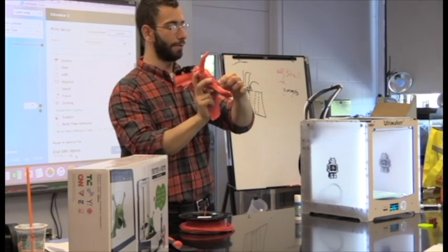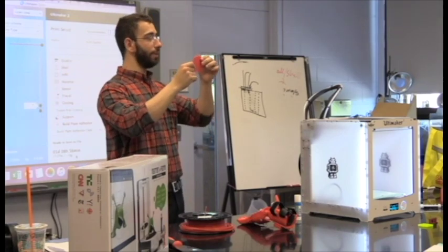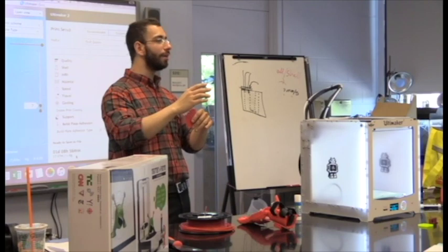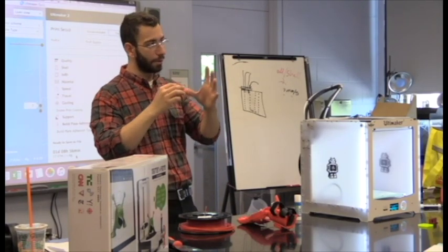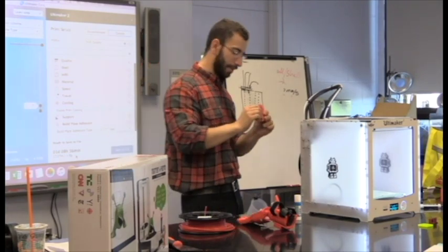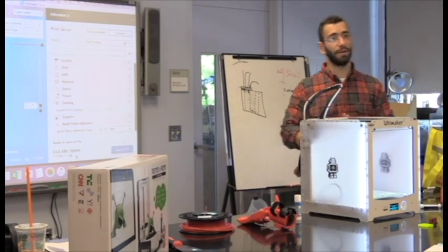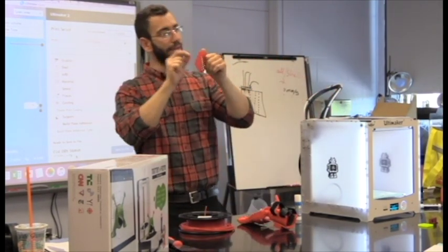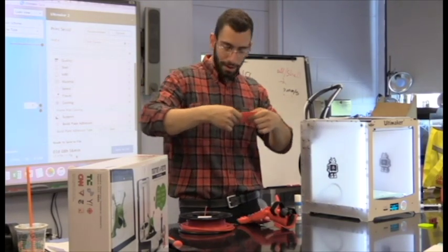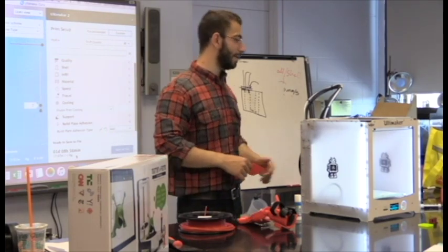And you see how it's perfectly flat around those screws? What we did is we mounted it first, put the screws in, and then we heated it up right here. It was hot enough that it didn't melt, but it was flexible. Malleable. Yeah, it was malleable, that's a good term. You can shape it, you can stretch it. Sometimes it works if you want to add a little lens in the middle: you make it up to tolerance, then heat it up, squeeze it in, and push it back in so it holds. There's a lot of cool stuff you can do. You need a heat gun for that.